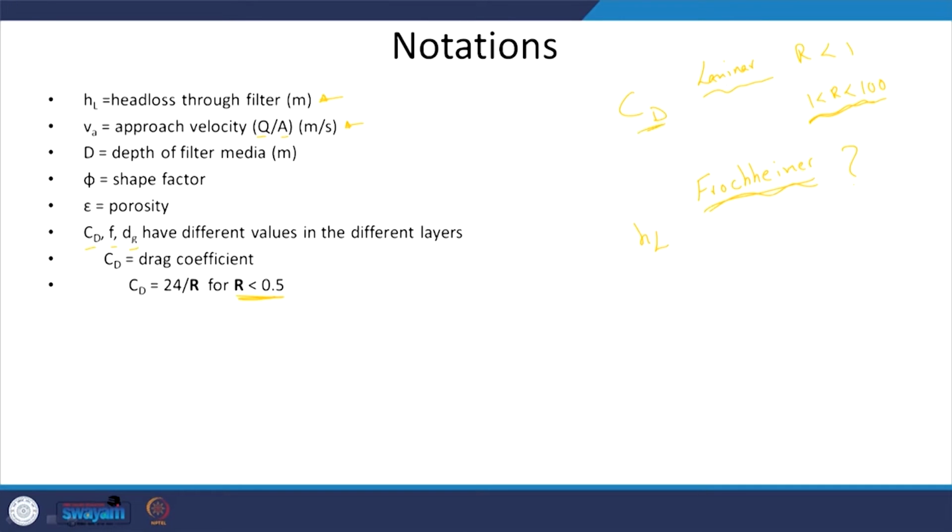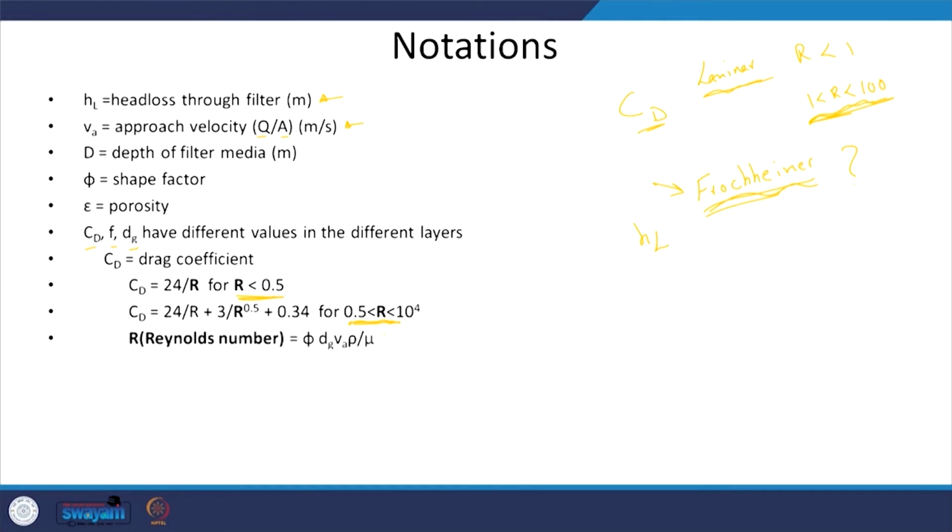Again, we will look at this. Head loss if it is laminar flow will be different, head loss if the Reynolds number is in this zone will be different. That is something to keep in mind. Again, do not look at me for the reference for this particular spelling, you should check the spelling. The Reynolds number can be relatively low, or in the transition or turbulent zone, but rarely will we get turbulent flow conditions. You can calculate Reynolds number obviously, and in this course I will give the relevant equations in a sheet, but depending upon which exams you want to pass, they might need you to memorize relevant stuff.